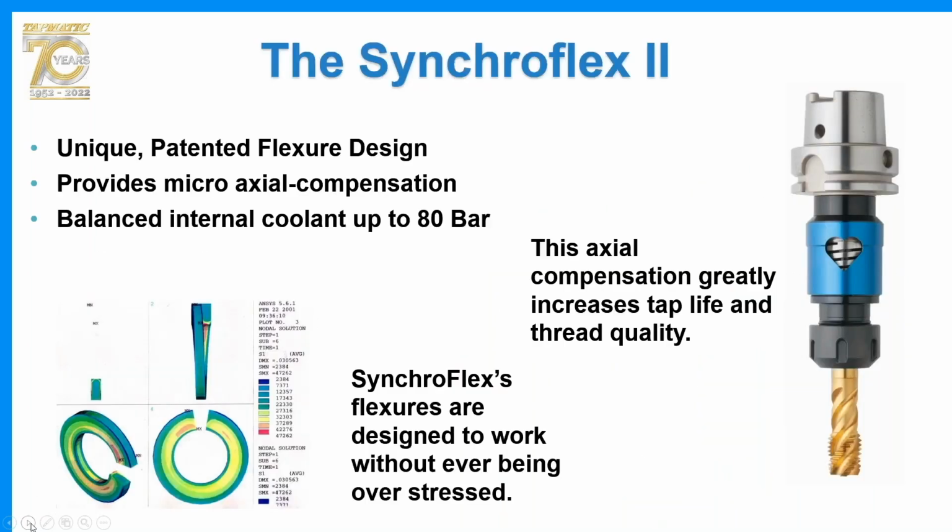To combat this problem, Tapmatic developed a unique holder called the SynchroFlex 2. This holder provides a microaxial compensation, which greatly increases tap life and thread quality. With this flexure design, they are designed to work without ever being overstressed, as they are mechanically fixed to a safe limit. With this, customers can expect to tap up to millions of holes with the SynchroFlex holder.